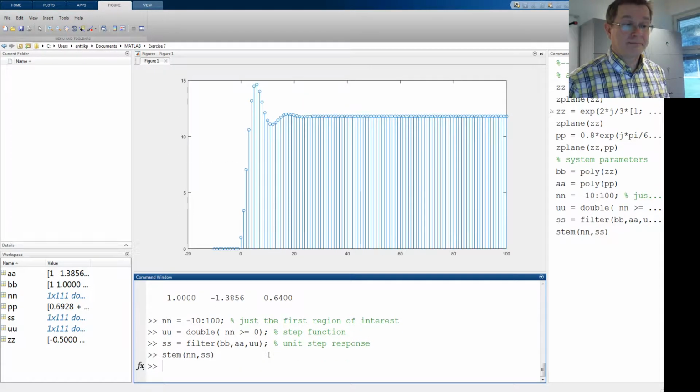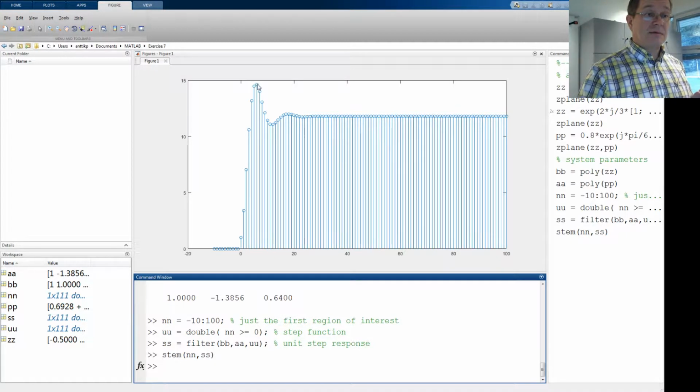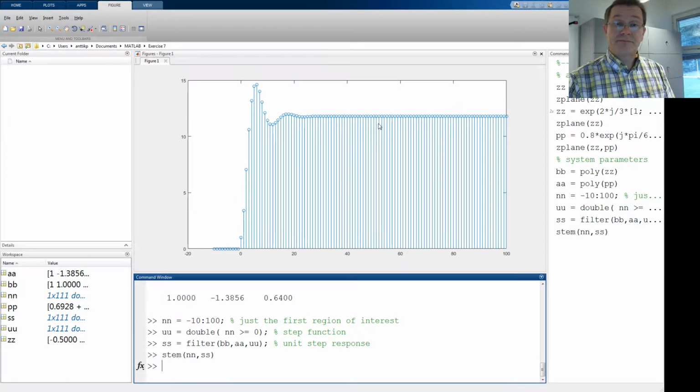There. Ooh, wow. Excellent. So this actually will settle faster than the original. So in this case, let's see, the final value would be more or less the last point here. So it has definitely settled within 2%. So within 2% accuracy, we can say that is the final value, but not better than that. This is just a guess. Okay, so I start with the final value, or the DC gain.